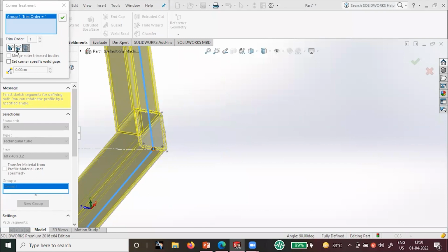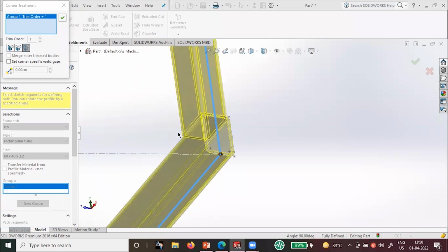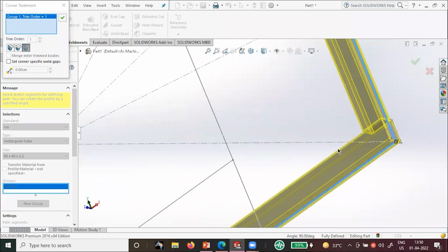Okay, so here my requirement is that it should be a finish. I'm not giving it here. These edges will be cutting my hand. For safety precaution, I'm giving it to smooth my corner. So that's why I'm using the end miter here. Select this end miter. Now it is smoothly connected. Now close it.